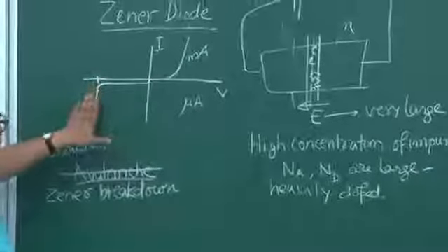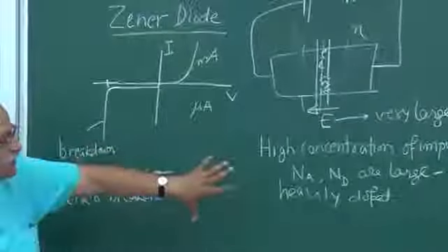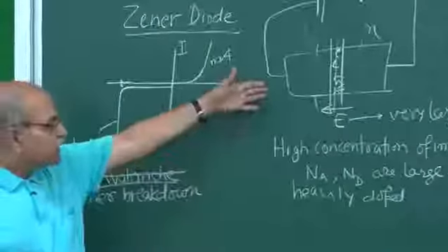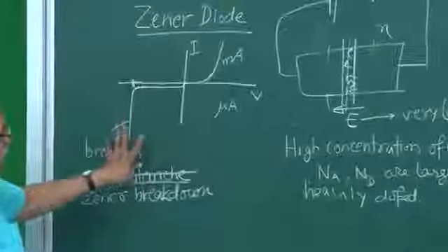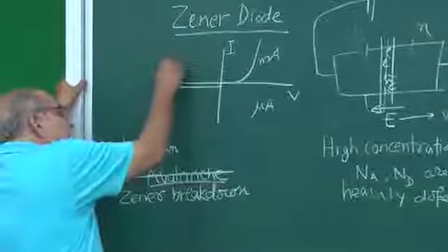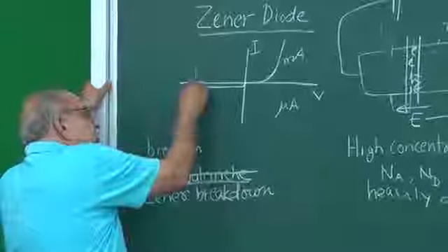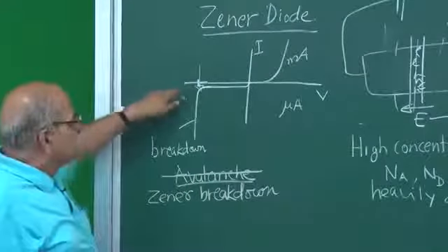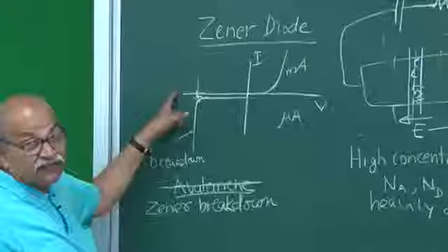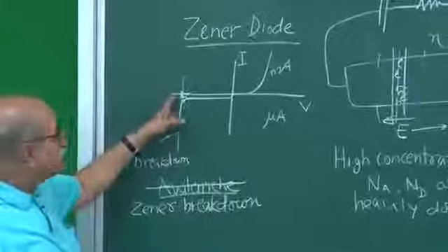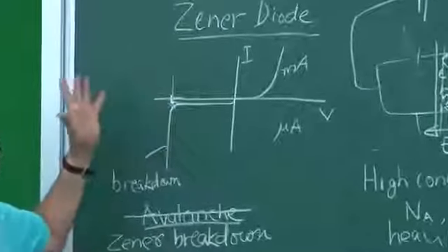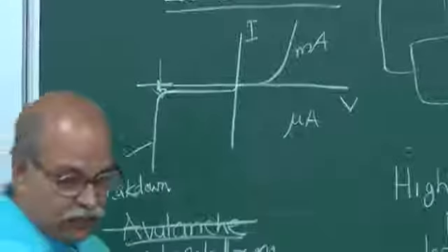So this is the kind of situation for Zener diode. It is always operated in reverse, and we will talk about its applications. It's always in reverse bias condition, and this is explored, that at a very sharply defined voltage the current will be there, and you cannot increase the voltage further in reverse direction. The current will keep on increasing, but this voltage will remain fixed. So that's the kind of diode we have.